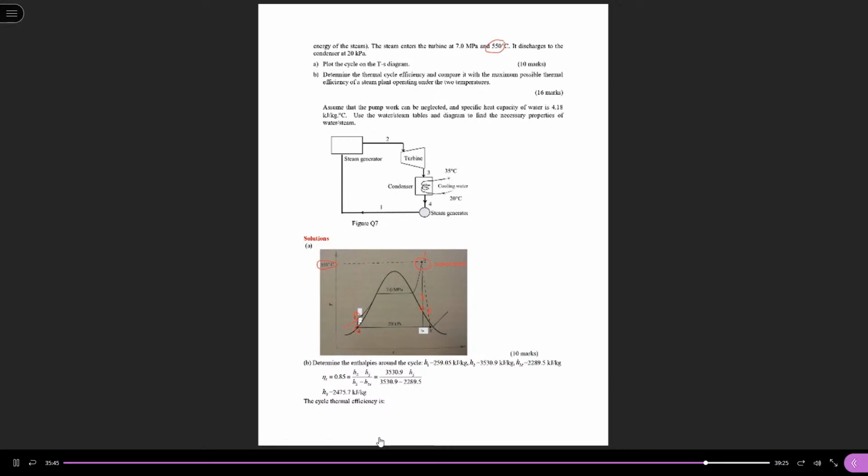According to the definition, the enthalpy increases. The actual enthalpy and entropy are larger than for the isentropic reversible process. So state 3 is here. If you put it here or here, I will also think it's okay. Just you have to use a dashed line, showing an increase of entropy compared with the ideal isentropic process.